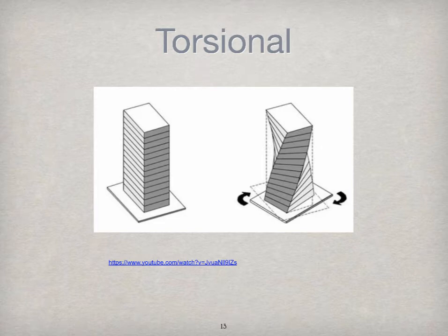Vibrations can be torsional as well. Torsional vibration is angular vibration of an object, commonly a shaft, along its axis of rotation. Torsional vibration is often a concern in power transmission systems using rotating shafts or couplings, where it can cause failure if not controlled.